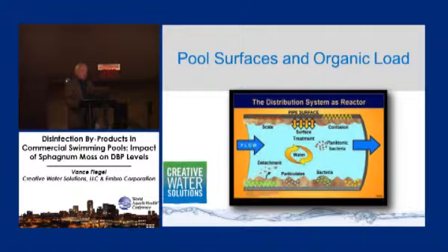Biofilm causes corrosion. You've got particulates within the surface material. That can be hair, cells, different things of that nature, whatever comes through that is not picked up by the filter. Within the filter, you've got all kinds of particulates that will be incorporated into the surface of the sand. Scale is another factor that causes adherence of biofilm. And then you've got detachment of this material also, which moves into the liquid phase of the pool until it gets filtered back out again.